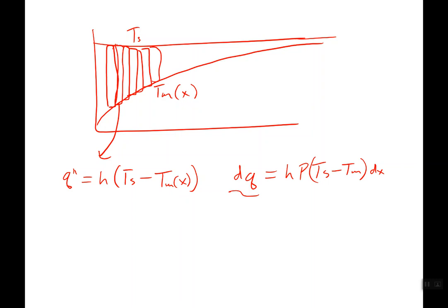It comes from the fact that our delta T is changing down the whole length of the pipe, so we really can't just say, for the entire pipe at least, that Q is equal to hA delta T, because our delta T from pipe surface temperature to the mean fluid temperature is different at every point along the pipe. So we've got to do some sort of integration.